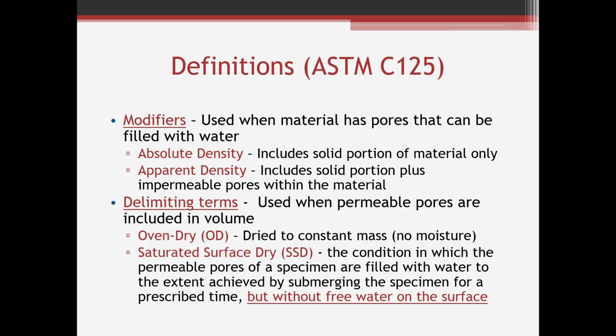One of the reasons we use the saturated surface dry density term is because with concrete aggregates, whatever moisture is absorbed into the aggregate pores is not available to hydrate the cement. So we don't count that moisture as part of the free moisture in concrete when we're doing those types of calculations.